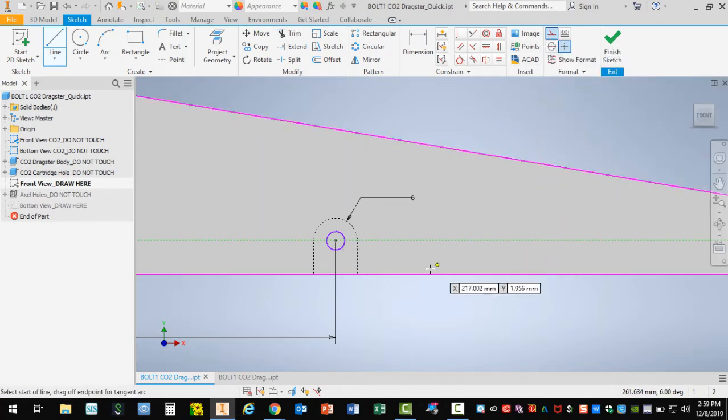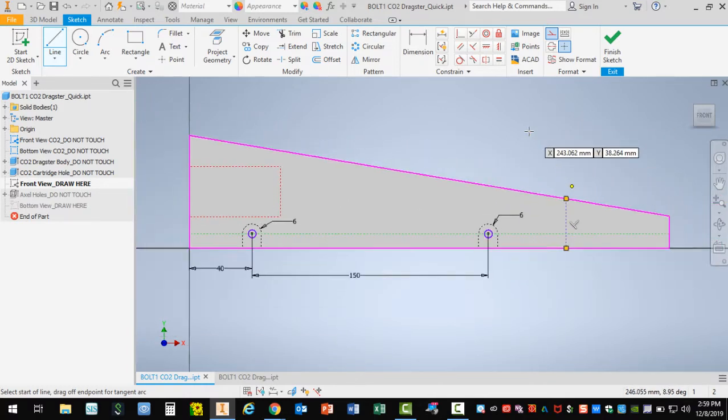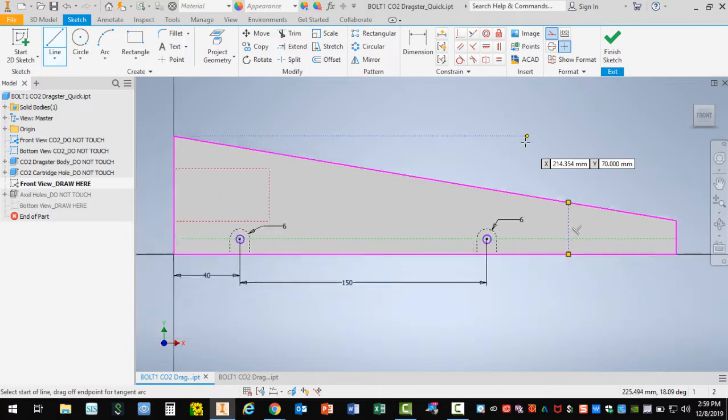I tell students to typically click somewhere in front of the front axle, anywhere along the bottom of your car. I'm going to single click with my left mouse button. Move vertical. Keep an eye on the degree. Do not worry about the length of the line. The degree should be set to 90. Once you get to the top of your car, left click again, and you can clearly see you have a construction line. If you double click your mouse wheel, everything should now fit onto your screen.